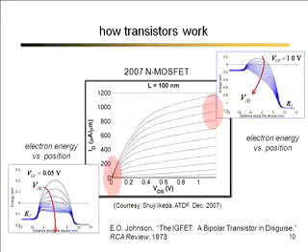Okay. If we draw an energy band diagram, there is still a potential energy barrier between the source and the channel. So current doesn't flow, unless we apply a large enough gate voltage. Each one of these curves is for an increasing gate voltage. As you apply a larger and larger gate voltage, you push the barrier down and turn the device on and current flows. But you can see now that once electrons get over the barrier, there's very little to stop them from going out the drain. So the drain voltage no longer matters very much once it's big enough. So in this regime, the current is more or less independent of the drain voltage.